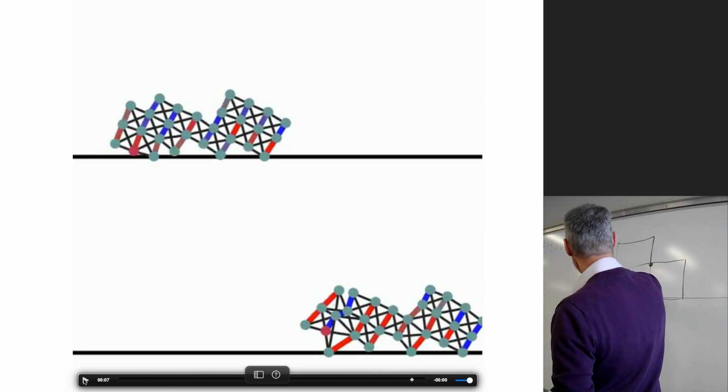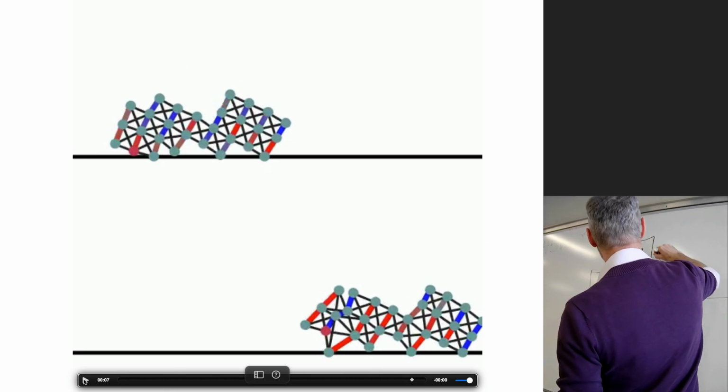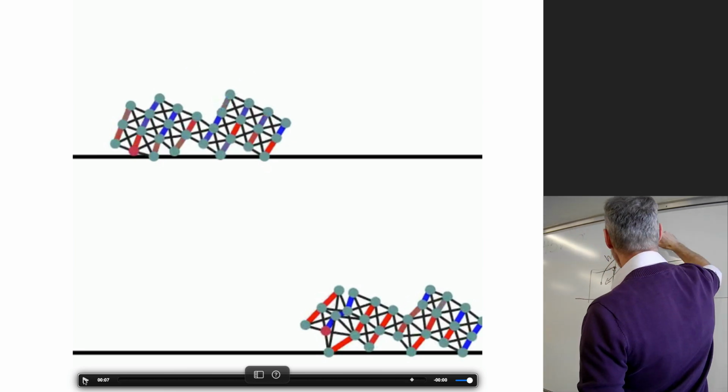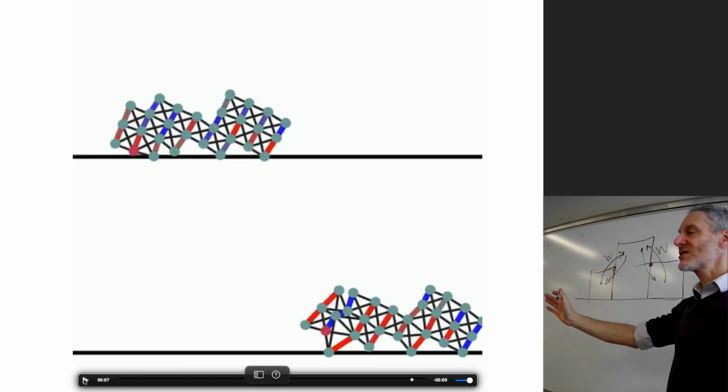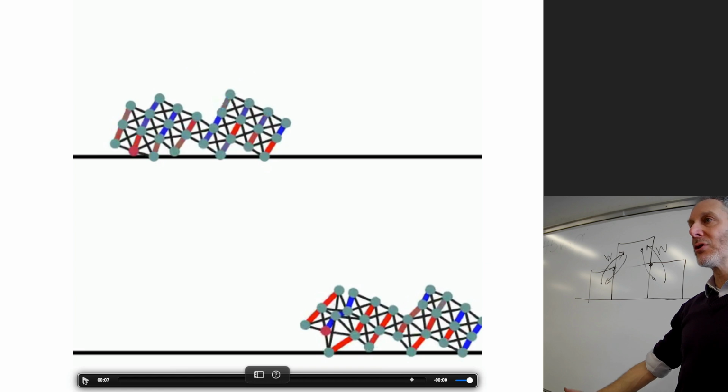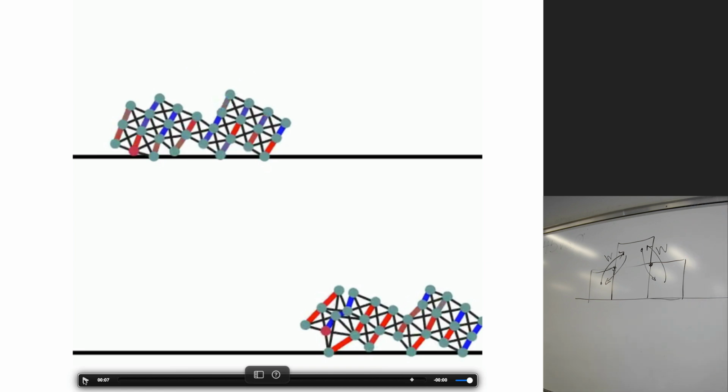We drop some sort of neural network controller into our robot. We've got a whole bunch of weights assigned to these synapses, and then we just run the simulator as we usually would for 100 time steps, 1,000 time steps. And then at the end, we ask the differentiable physics engine to tell us how well did the robot do. Here's where things start to change.